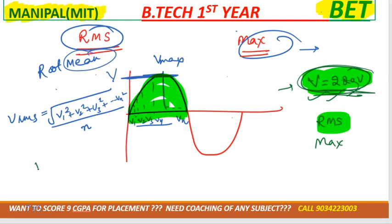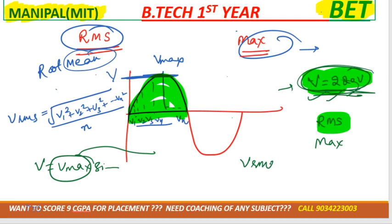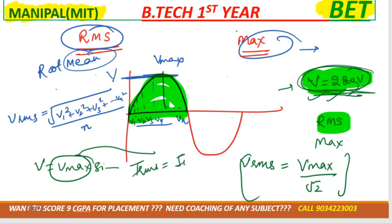Okay. So whenever they provide you the standard equation V equals V max sine omega t, we'll have V max. We need to convert it into VRMS, and the standard formula for this is VRMS equals V max by root 2, or similarly I can write IRMS equals I max by root 2.